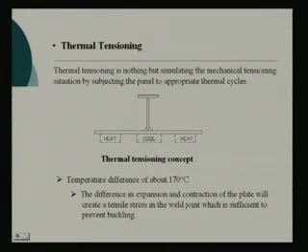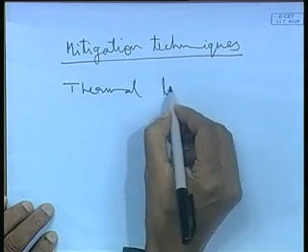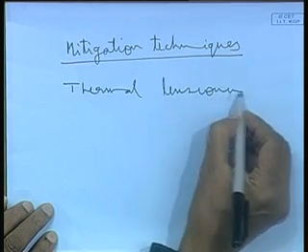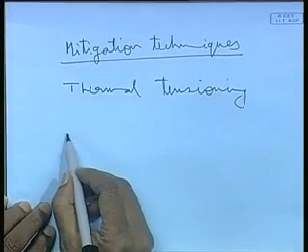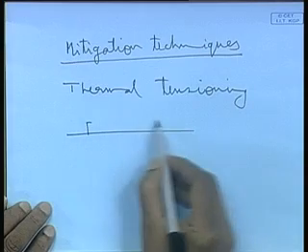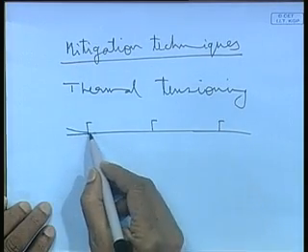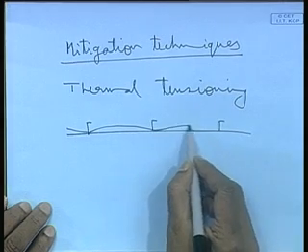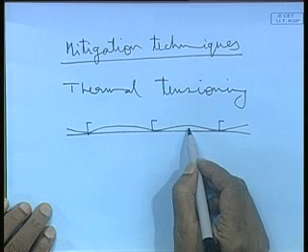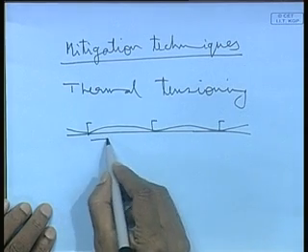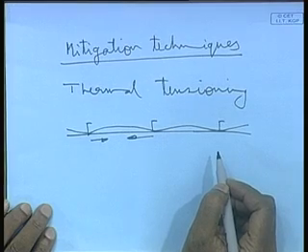Essentially, what we have seen is, when this is welded, apart from angular distortions, there is a buckling deformation, right. A buckling deformation is taking place. Now, buckling is because of what? Because of compressive forces developing. So, it causes buckling deformation.